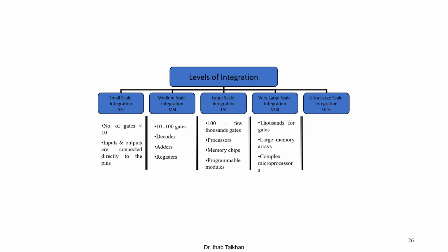The levels of integration depend upon the number of gates and the accessibility from the pins to your input devices, components I mean. In small scale integration, SSI, the number of gates is less than 10, and the inputs and outputs are connected directly to the pins.